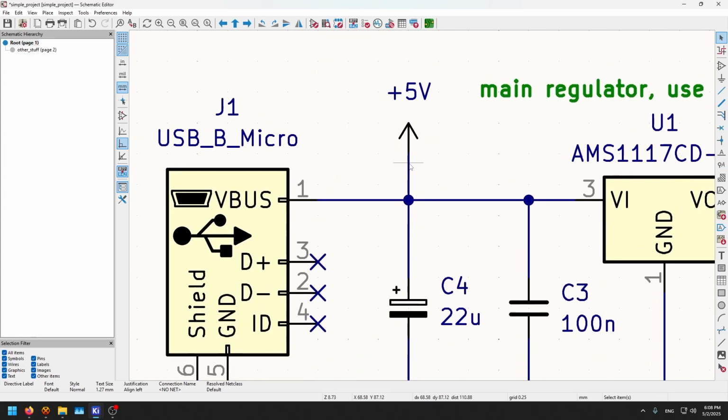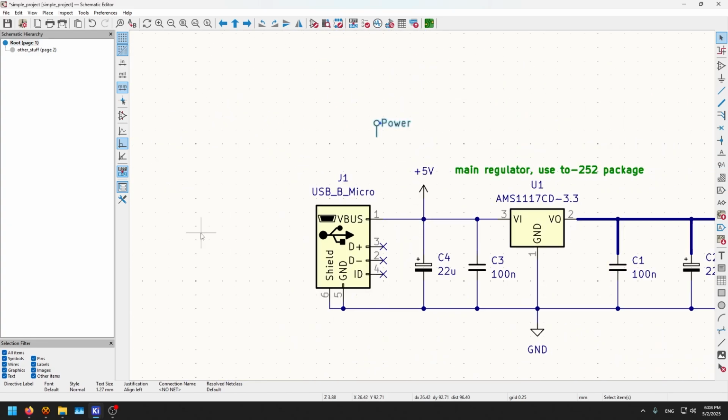Okay, so what if I have multiple wirings and multiple signals? I want to assign one net class for all of them. What should I choose? Either I copy and paste this all over the place, or I go to this place right here to draw a rule area, basically like that, and I'm going to include, let's say, all of these.